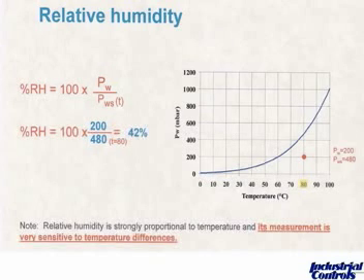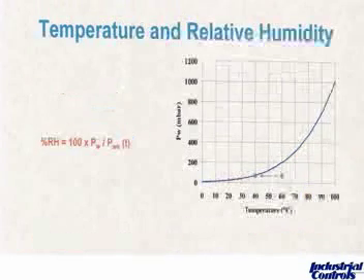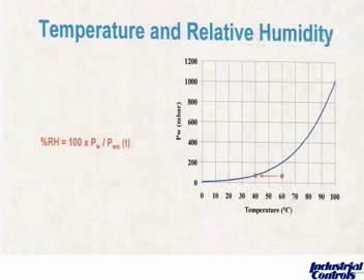And again, I'm just trying to emphasize the temperature effect in these next few slides. In this example on the slide, what we're showing is a temperature of 60 degrees Celsius. And without adding or taking away any moisture, if we were to reduce the temperature to 40 degrees Celsius, you can now see that we are at a saturated condition where we weren't before.